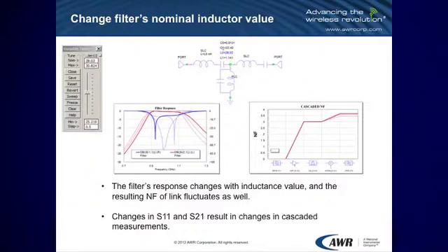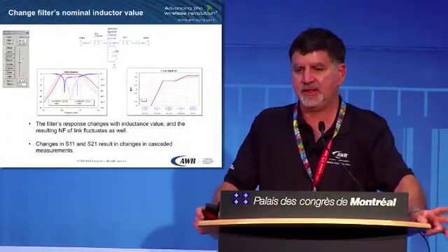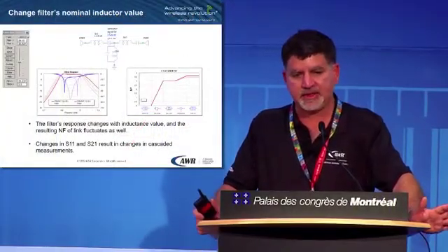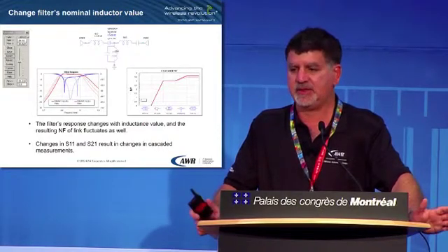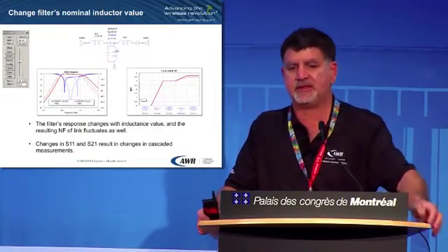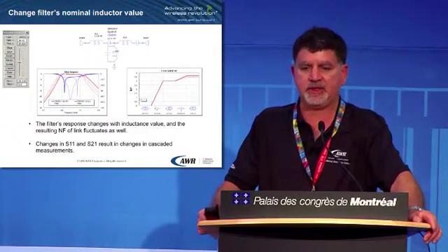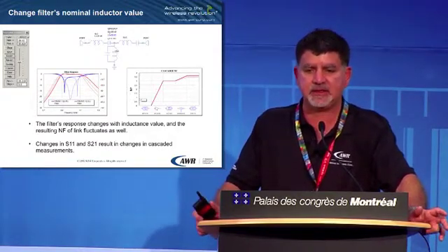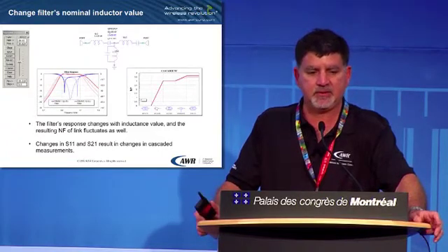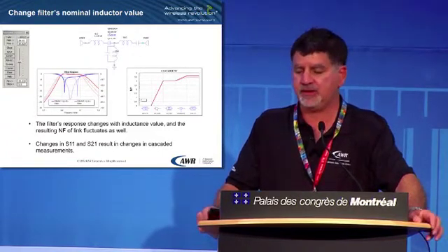So now we have two cases where we have differentiated from the typical Excel spreadsheet. One, power spectral density running through the LO path, causing noise figure to go up, a higher power spectral density than thermal. Another instance here where we're tuning or optimizing on an inductance value, changing the S11, hence changing the noise figure.